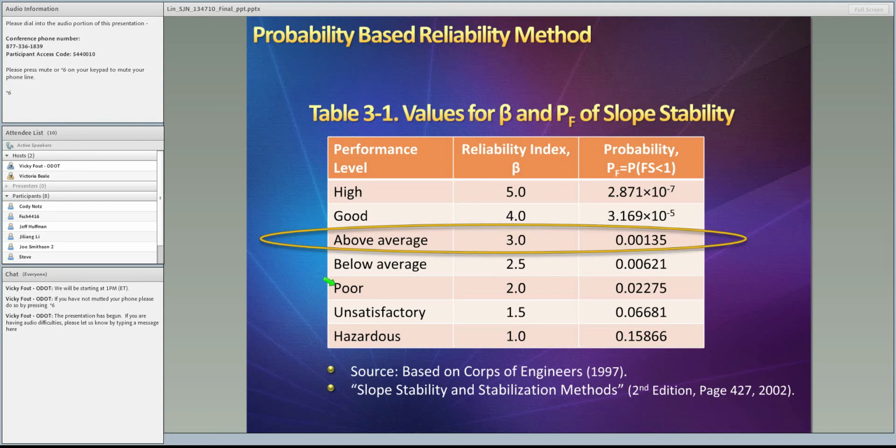So how do we realize the flowchart in a program? First, we import the slope and geoshaft geometry in C++. Second, we read in three data files: cohesion, friction angle, and unit weight. All of them follow a log-normal distribution. Also, as I mentioned, the load transfer factor is uncertain, so we read in the bias or eta, which also follows a log-normal distribution.